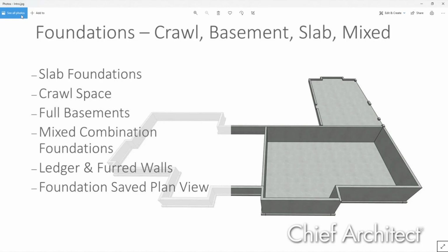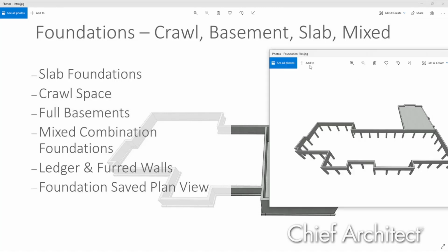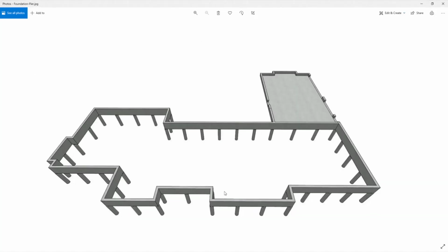So when you build your foundations, there's an option to build it on pier. Do you use that option, Derek? I don't. Okay. So when you build your foundation on pier, here's a variation of the foundation I built on pier, which I just built using the default settings. Then all of those objects can be manipulated. You could pull the wall over. You could copy and paste those piers. It comes in at the right elevation.